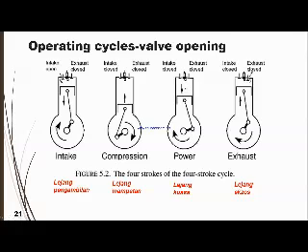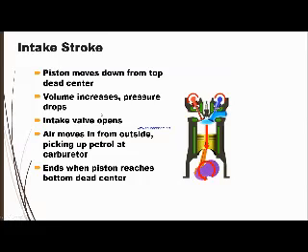fuel, and then combustion happens. Because there is no way out for the gas and the pressure, it is going to push the piston downward and do another half rotation and deliver the power for the engine. And then at the end of the process we have the exhaust, where the second valve will open to allow all the gas to go out from the chamber, and then we repeat again from the first, which is the intake.